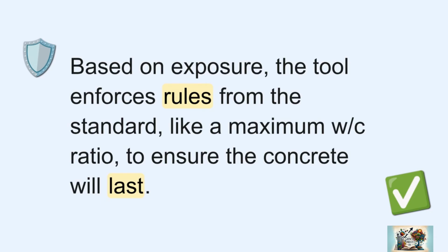Next, it kind of acts like a safety inspector. You tell it about your project's exposure conditions, like is it near the coast or in a place that freezes a lot, and it automatically enforces the rules from the standard. It'll lock in things like a maximum water-to-cement ratio to make sure that concrete is going to last for decades.